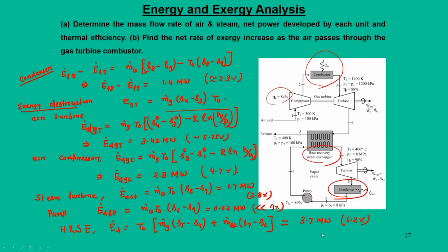Exergy analysis is quite justified, because the second law also tells us that some exergy is always destroyed; we cannot recover it completely. However, for this present problem, exergy analysis justifies this fact. These numbers are quite realistic, and based on them we can take an appropriate decision of combining a steam power unit with a gas power unit.